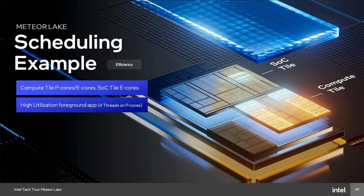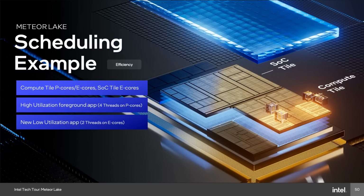Let's say that I'm running some CPU intensive task on my Meteor Lake system, right? I have 4 threads and I keep my P cores active because I really need that performance. Now if some audio playback or video playback started, since I have my compute complex up, there's no point in waking the SoC complex, even though the work could have fit in there. Then we recommend to the OS to use the E-cores on the compute tile to do that low usage work, right?